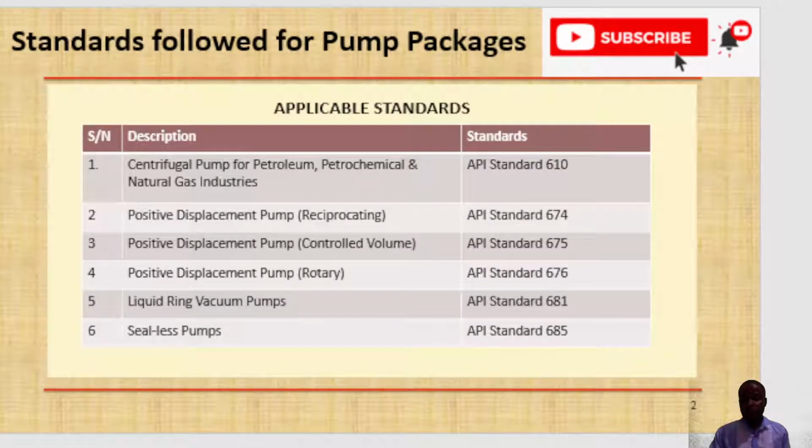Before we continue in the technical evaluation of mechanical data sheets for centrifugal pumps, you also need to be familiar with other standards that are followed for pump packages. We have the following applicable standards. We have API 610, which is the standard followed for centrifugal pumps for the petroleum, petrochemical and natural gas industry. We also have API standard 674, which is the standard for positive displacement pumps, specifically reciprocating pumps.